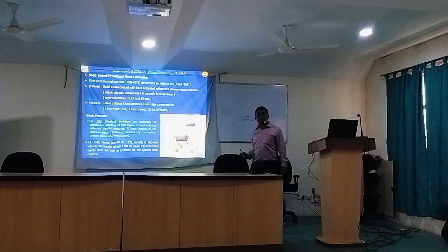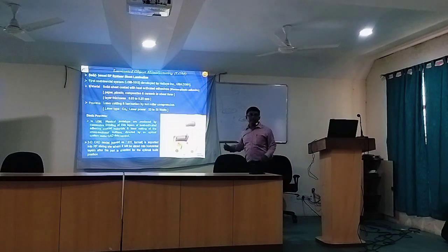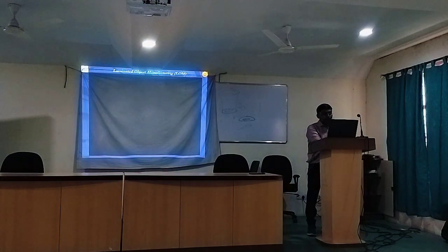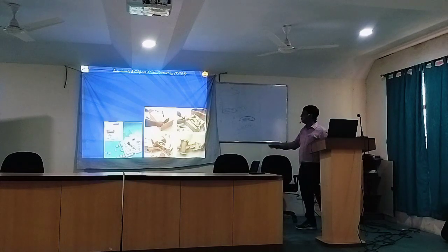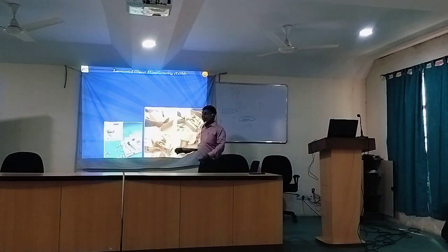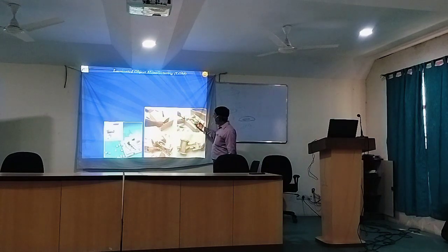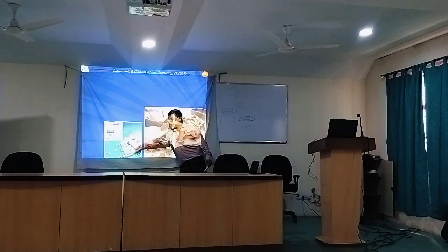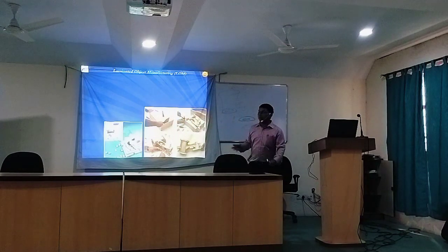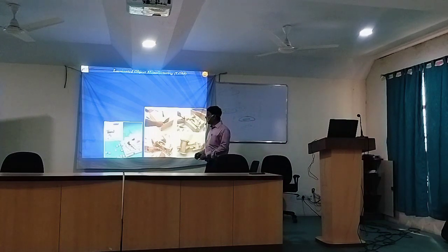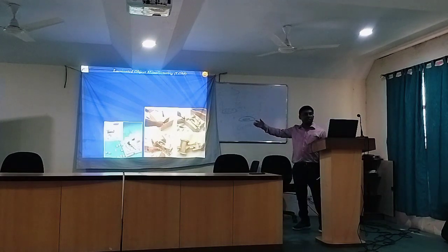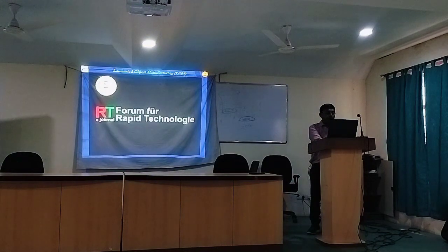So this process will continue till the top of the paper. Okay? So this is a very simple lamination process. And ultimately, this is the product you will get, like this box. Now remove the unwanted portion; the cross hatch makes small tiles that you can easily remove. Otherwise, due to the totally solid form, removal is not that easy. That is why you have to cross hatch, so that you can easily remove the small tiles. And obviously the wastage of material is huge in this case.